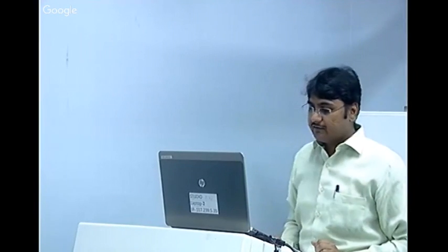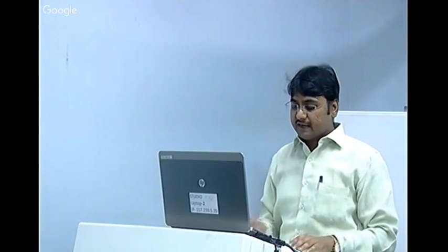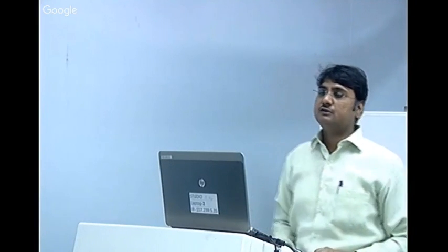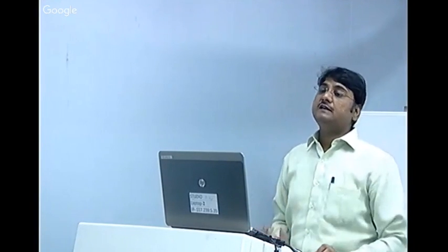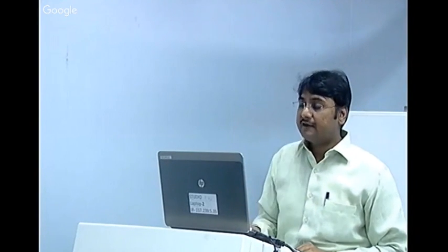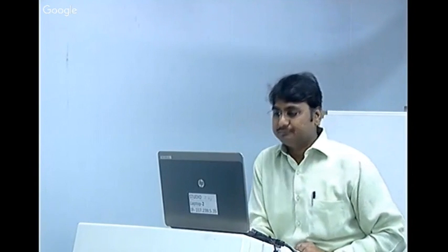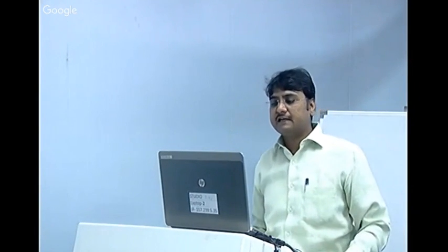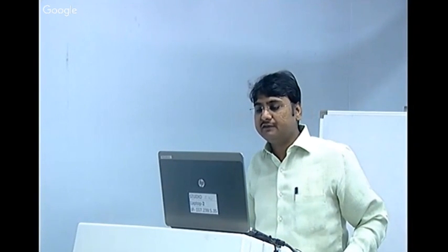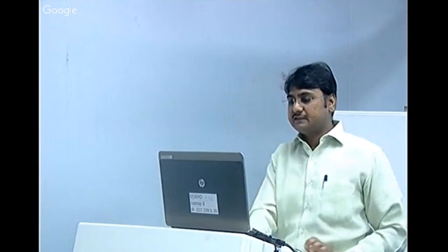Another thing which I will tell you, the building has its natural time period. Natural time period means the time period in which the building will oscillate. In that natural time period, the building also has a natural frequency. Every building has a natural frequency. I'll tell you about this later. First, the main challenge is that the building should be able to withstand small intensity of shaking with limited damage, and with no collapse under high intensity of shaking.